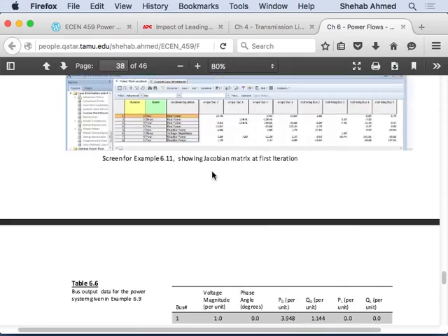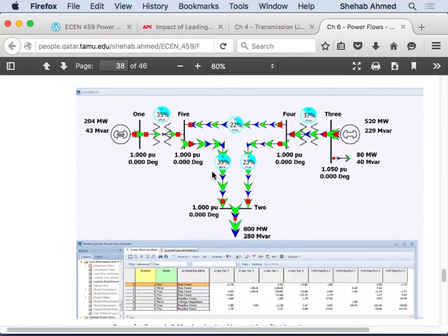At bus 2, in addition to real power, we also have some reactive power being drawn there, right? So we will see from the equations shortly that reactive power and voltage magnitudes are directly related. And we saw that before from the idea of power factor correction, right? When you did power factor correction, you had an induction motor, for example, and you put a capacitor across.